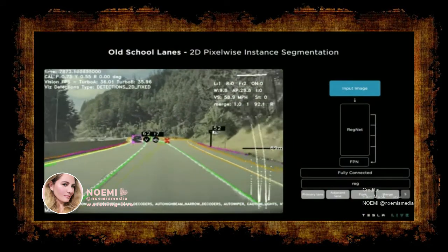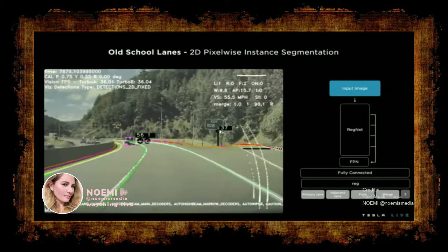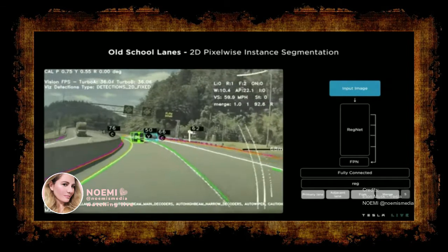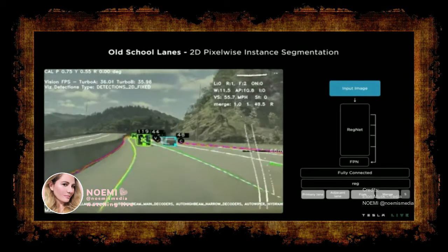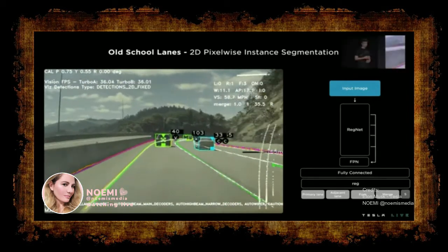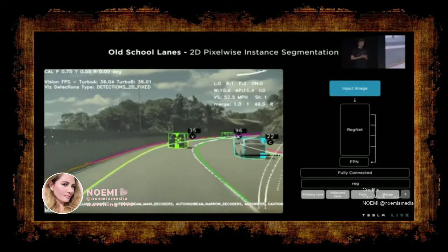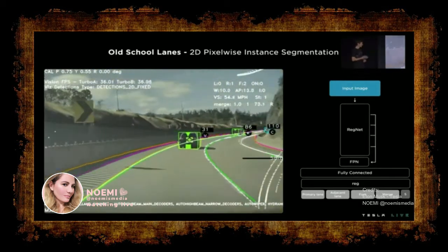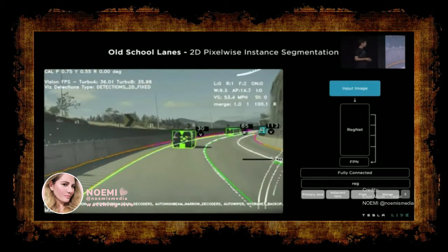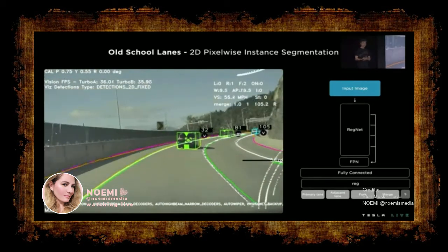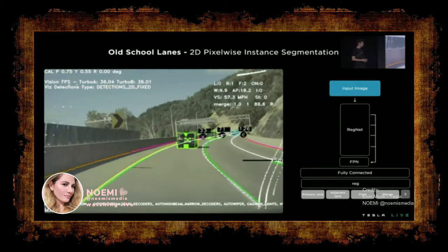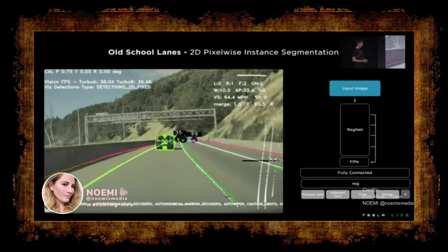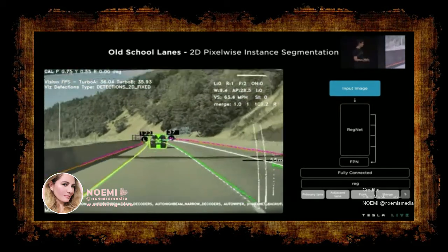In the early days of Autopilot, we modeled the lane detection problem as an image space instance segmentation task. Our network was super simple, though. In fact, it was only capable of predicting lanes of a few different kinds of geometries. Specifically, it would segment the ego lane, it could segment adjacent lanes, and then it had some special casing for forks and merges. This simplistic modeling of the problem worked for highly structured roads like highways.